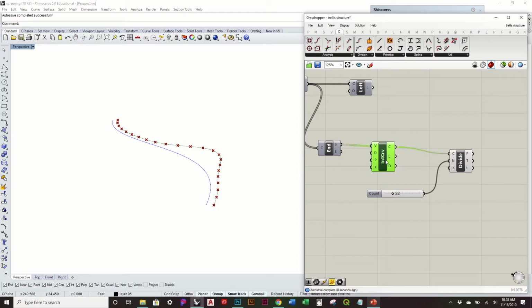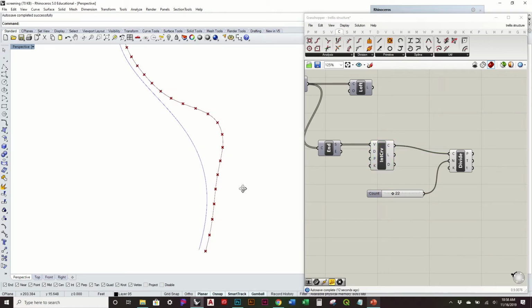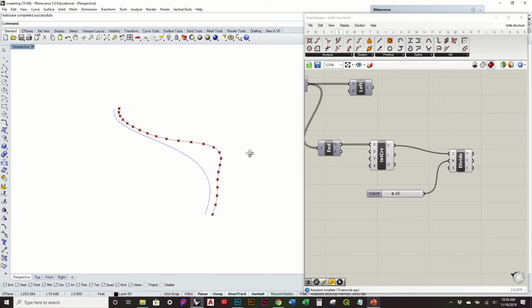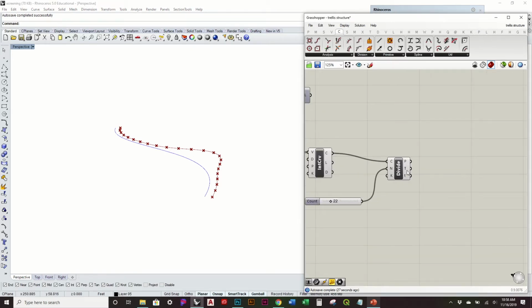If you want to have more points, you can continue this process, but this is basically just allowing us to create a profile curve. If we have 2, it's just going to create a line segment. With 3, we can add more curvature to it.